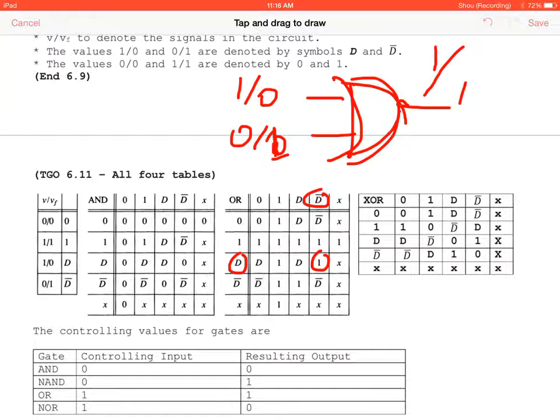So in a weird sort of way, you have 2 errors, but you have propagated the correct value on the output. So this is why testing can be tricky, and that's why coming up with your own set of vectors without doing ATPG covers only 70 to 75%. Because often you'll still get correct values on your output even though you have 2 errors on the input. So using these algorithms to try to narrow down your fault is very useful and will save you tons and tons of time.